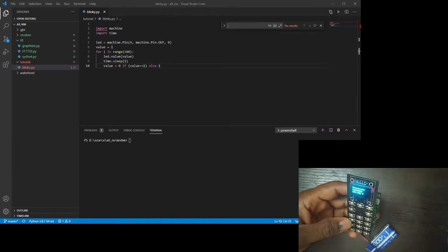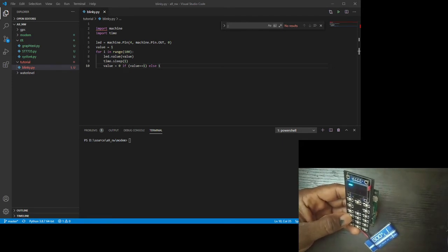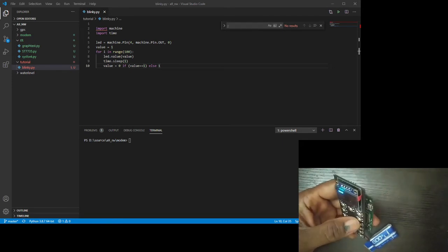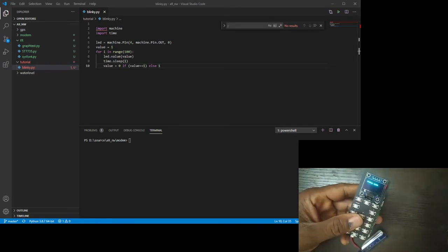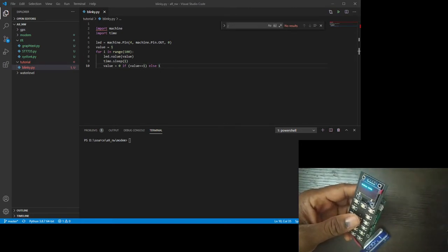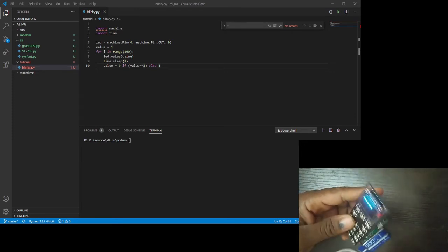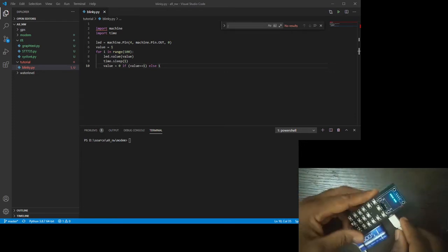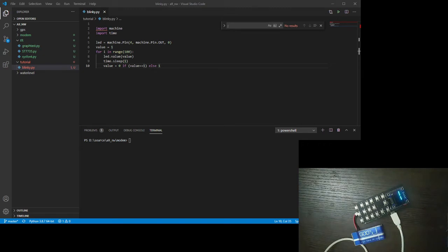Before we do that, you have to switch the board to debug mode. So there's a special code for that. You dial 4444, that's 4 in 4 places, and you press OK. So that will put the board in debug mode, and once it is in debug mode, you can now connect the USB cable and be able to have access to it.